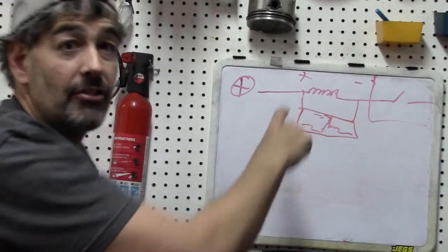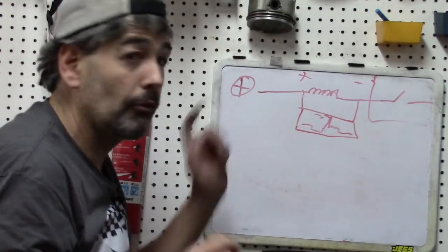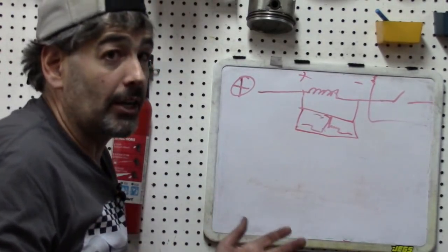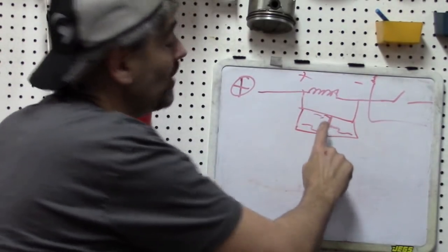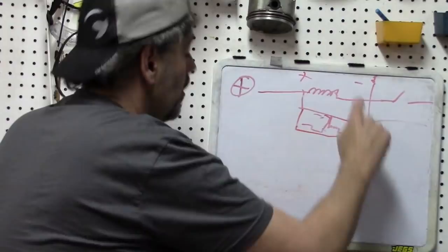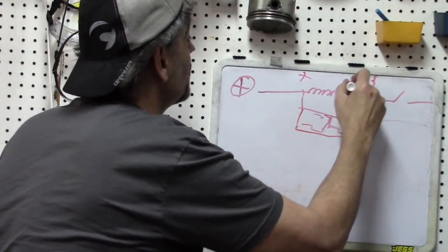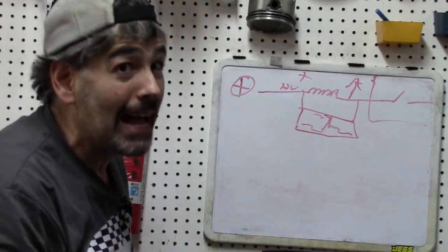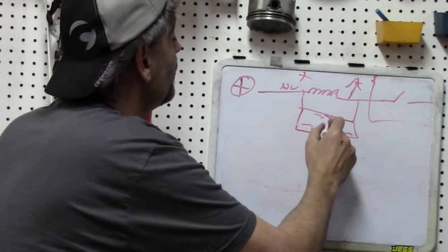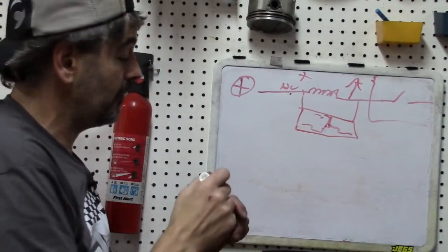This side of the circuit is actually positive 12-volt feed no matter what at all times: running, key on, engine off. The spike that we're seeing is actually an inversion from the huge voltage spike here versus 12 volts here. That's actually what it is. This is not on the positive side of the system.